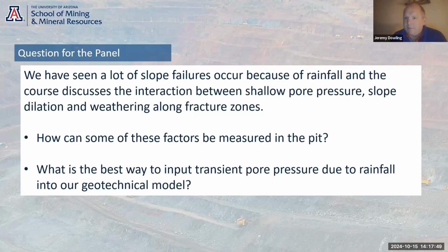And we've had some good success where we've been involved with FLAC models that have initially just been calibrated with the regional piezometric data and the deeper groundwater levels, and the deformations in the slope can't be replicated.